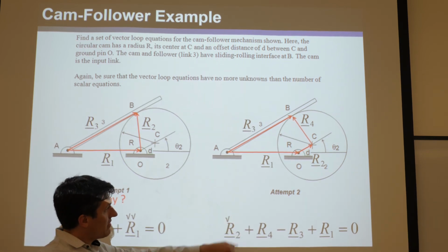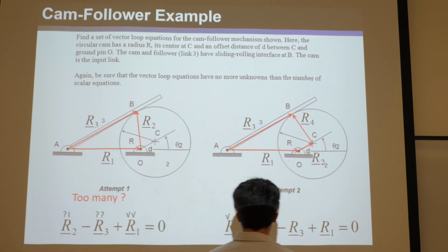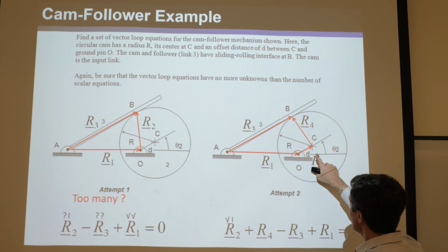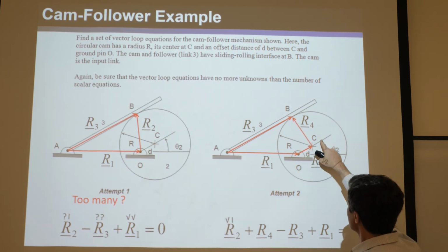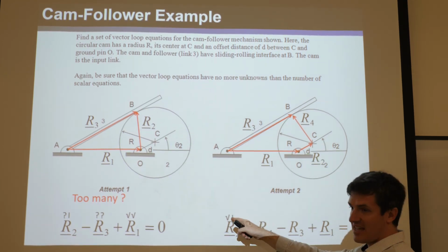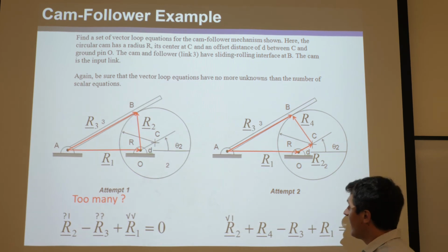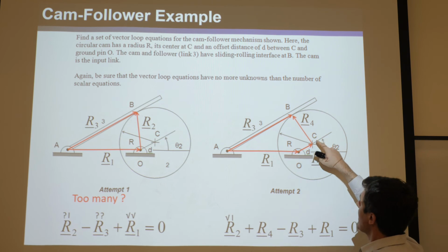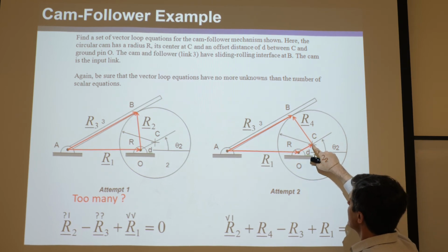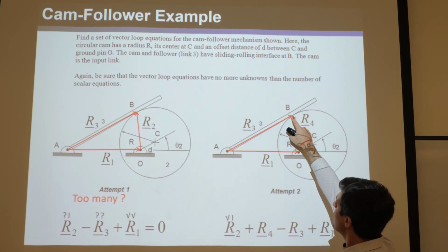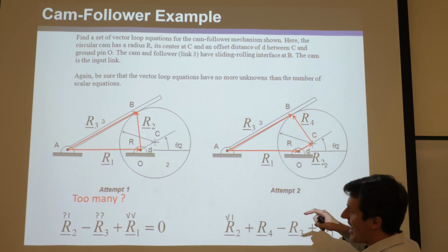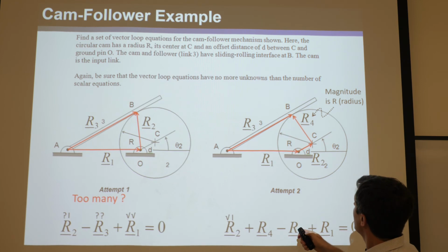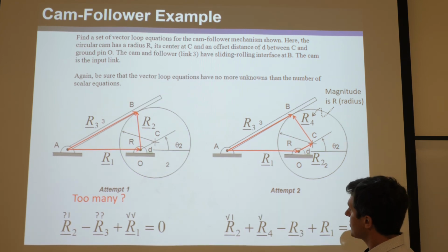All right. Do we know its angle? Yes, it's the input. Okay. So since here's the tail, you draw a horizontal line and you draw the angle up there, which you can see there is theta 2. Okay, and that's the input. So that's I. Okay, R4. Aha. Do we know the magnitude of R4? Well, yeah, it's always going to be from the center of the circle to where it touches this bar. Okay, and so the magnitude, that's always going to be R, or the radius of the circle. So we know that. Magnitude is R, the radius of the circle. So that's a big check.